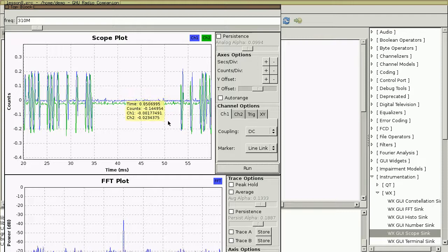transmission. You might call it a CW transmission, which is what folks call Morse code, but in this case, since it's produced digitally by a digital electronic circuit, and it's produced much faster than a human could, I would definitely call this on-off keying. It doesn't look like the frequency changes over time. When we look at the average in the FFT plot, it's very consistent and narrow, a very narrow band signal.